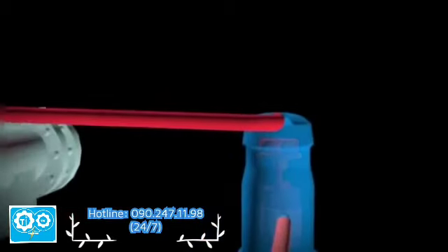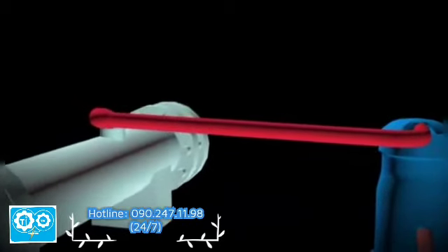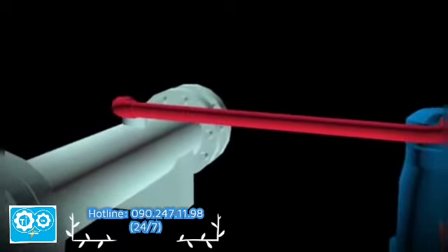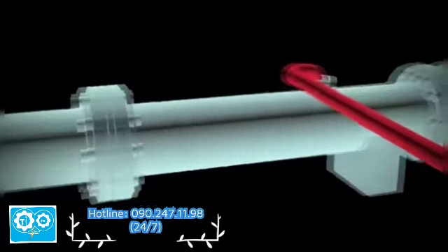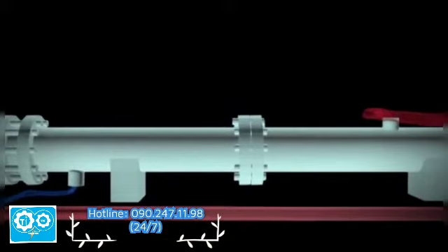Condenser. The refrigerant in high pressure gas enters the condenser at a temperature higher than the temperature of the condenser water. In the condenser, the heat is eliminated to the condenser water from the cooling tower through the process of convection and conduction. After the heat is removed, the refrigerant in high pressure gas is condensed into a high pressure liquid when it comes out of the condenser.